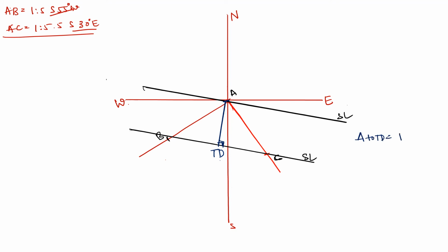We'll get the true dip amount if you measure this angle, and if you measure the angle SATD, then we'll get the true dip direction.